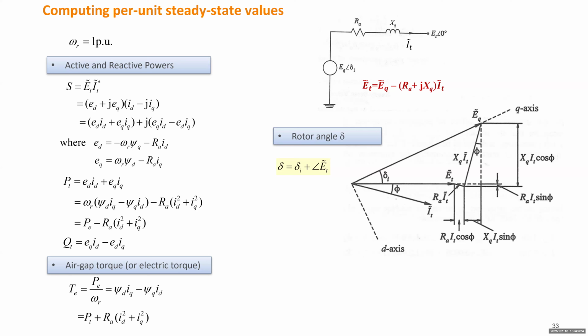All right, so we can draw a phasor diagram based on any equations about the phasor quantities. I assume everyone is very familiar with how to come up with this phasor diagram. To draw the phasor diagram, we need a phasor or vector representing each item in the equation, which has a complex value with real and imaginary parts. First, you need to define a reference. If we assume ET has angle 0, we draw the reference, which is the x-axis, with 0 angle. So this will be ET. Okay, so start from ET.